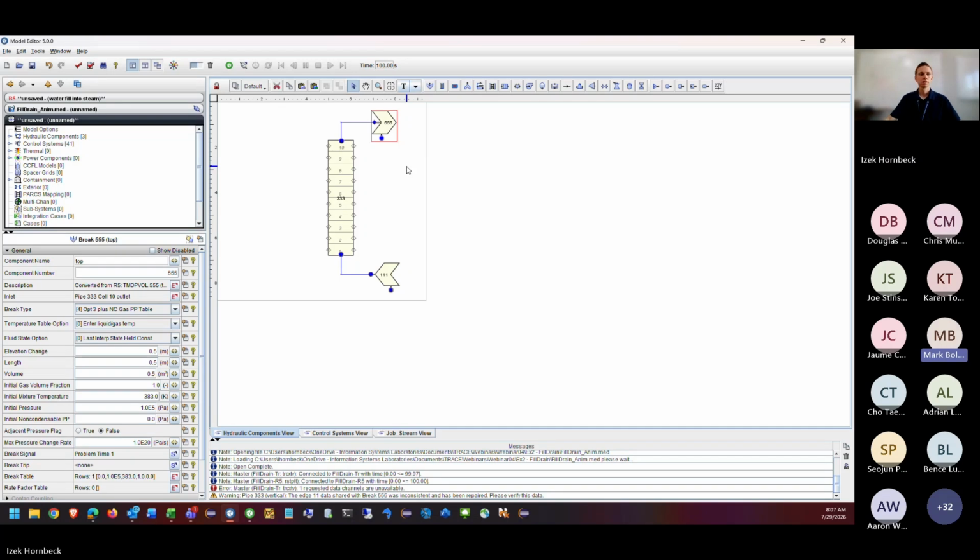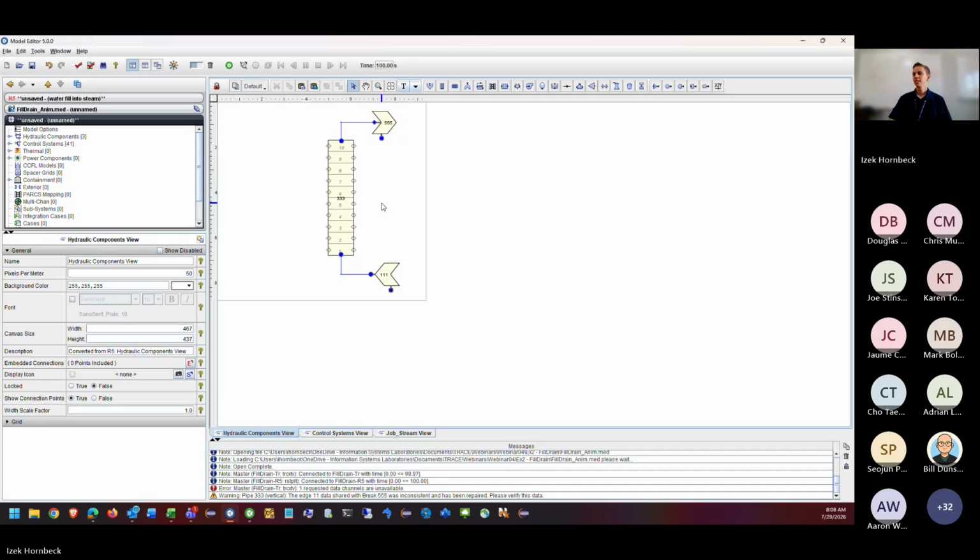Does that help? Yeah, that's very helpful. And I think you can sometimes have a time-dependent junction not connected to a fill or a break. How would that be handled? That converts just into an interior pump component in trace. Trace has a 0-celled pump component corresponding to the time-dependent junction, and that's what it gets converted to if it can't be merged into a fill. Okay, I didn't know that. Yeah, thanks, that's what I was wondering.